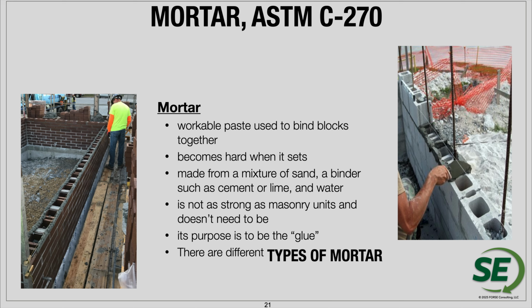as the overall mortar that would be used when it's placed within the assembly. And the reason for that is, when it's tested alone, it's going to have a higher water to cement ratio, and a higher water to cement ratio is going to yield a lower strength. The mortar, when it's tested alone, is also going to just be mortar cubes, which is going to be kind of a 1-to-1 ratio of size. When the mortar is placed within beds within the masonry units, it's really going to have approximately a 3-to-1 ratio of height to thickness.